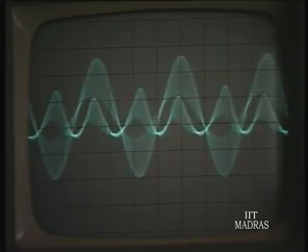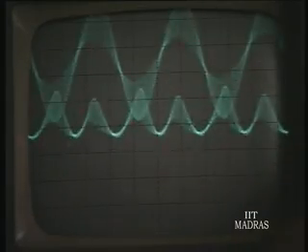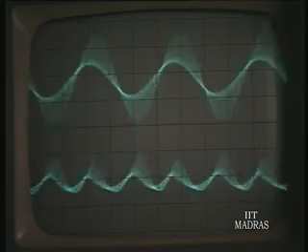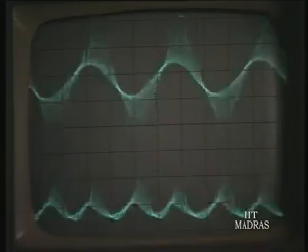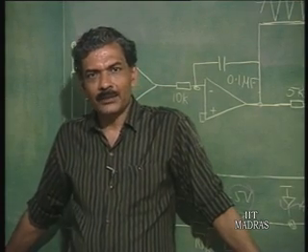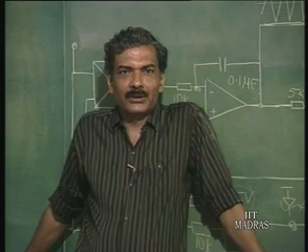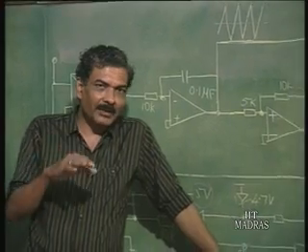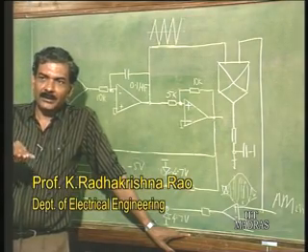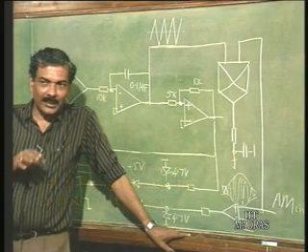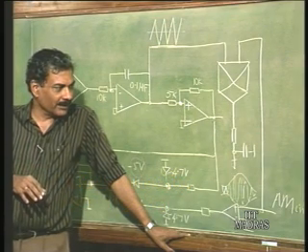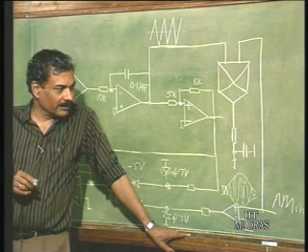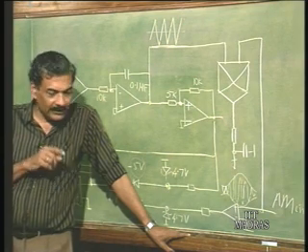You can see the low frequency component is already coming. Okay. We will later see the AM detected output. Just so now that you have seen that the multiplier output is going to contain 2 omega_c plus or minus omega_m and the omega_m component that is separated by the low pass filter. So, now you are going to see the omega_m component on one vertical plate, and another one is the AM itself.